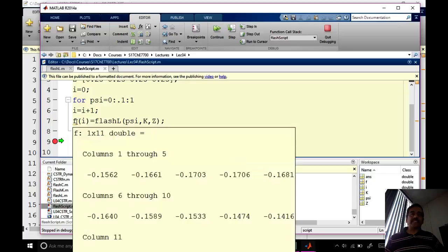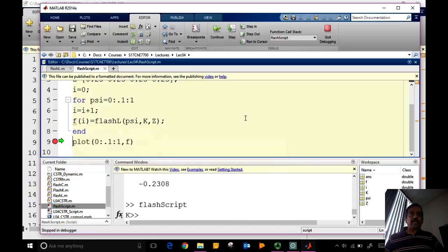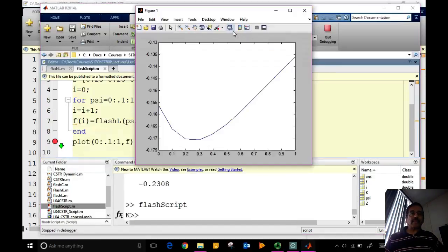So f would be like this. And there is my function. Okay? Now, do I have a root between 0 and 1? No, because all of them are in the negative. So my k values were not right in the sense that they're all in the liquid phase or vapor phase. It's not separating into 2 mixtures.